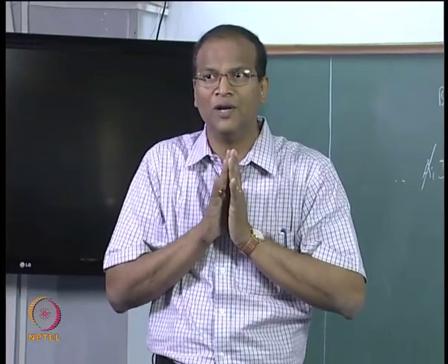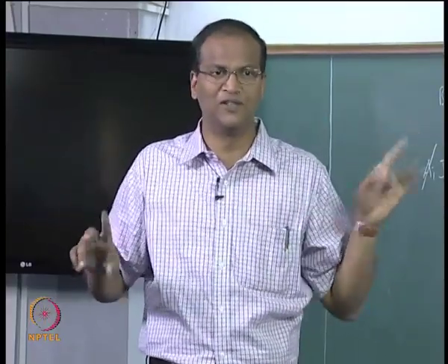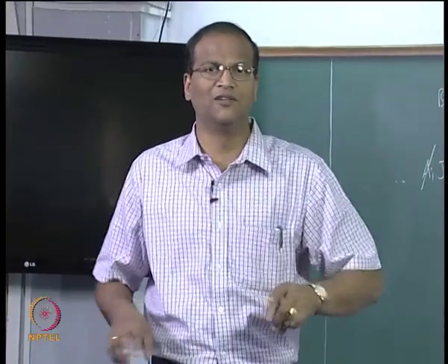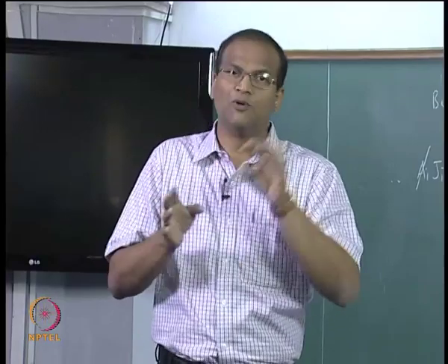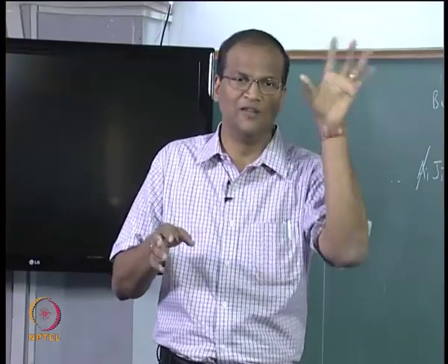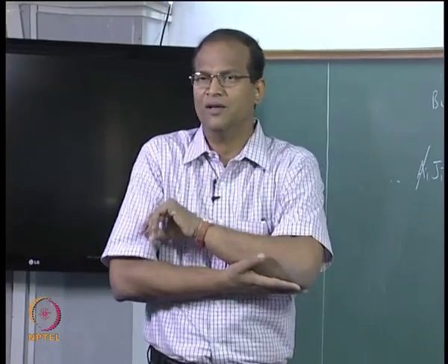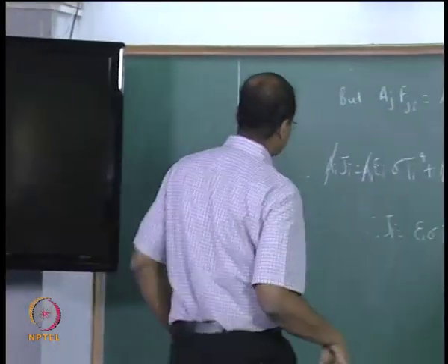You will be in trouble if you have a concave surface. Otherwise, the first term F11 for the first surface, the second term F22 for the second surface, the third term F33 for the third surface will all be knocked out if you have plane or convex surfaces. Suppose I give you a sphere within a sphere, cylinder within a sphere, or cylinder within a cylinder, then some F22 may be non-zero, and then you have to consider this. Okay.